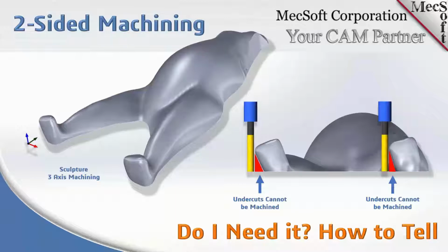So if you see an undercut, then you need to make a decision whether you are going to flip it, or whether you're going to leave it the way it is and do it manually from the other side, or how do you want to do that? This particular example is a sculptor, so they just decide they're going to do it on one side, and then they'll take the part and hand sculpt out the undercuts. So basically, anytime you see an undercut or feature on an opposite side, you're going to need flip machining if you're going to machine it.